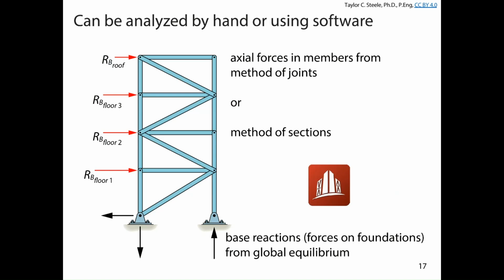Okay, so you might use method of sections, you might use method of joints, you might use STAAD.Pro. What I want to talk about a little bit is differentiating between indeterminate structures and determinate structures and different types of bracing arrangements. Okay, this is what's called a zigzag bracing arrangement. The name's probably pretty obvious. It kind of zigzags back and forth between the joints of the truss.